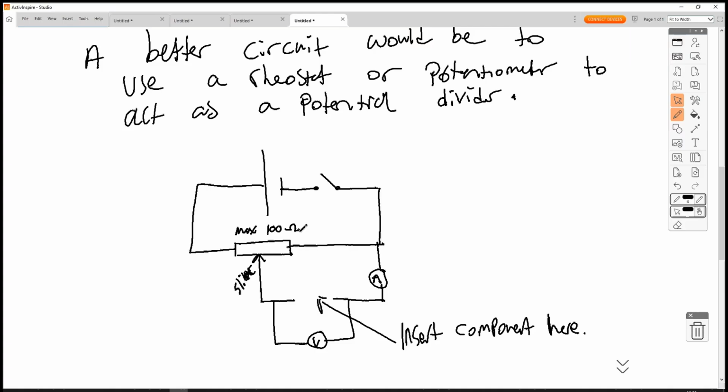The wire has no resistance, so it's a short circuit. So the wire has 0 volts. Our component is in parallel with a short circuit, so our component has 0 volts. And therefore, no current flows through our component because current will take the path of least resistance and go straight back to our power supply.